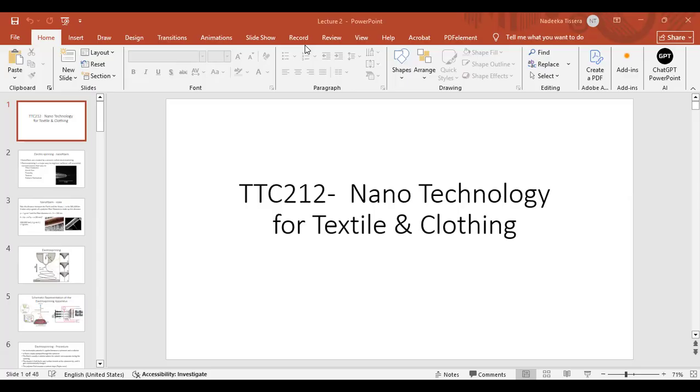In the top-down approach, you start from a bulk material and make it into smaller materials until you come to the nanoscale. Or else you can start from the atomic scale, assemble them, make cells, cubes, crystals, and molecules, and then keep assembling these things until you arrive at the nanomaterial. That is the bottom-up approach.